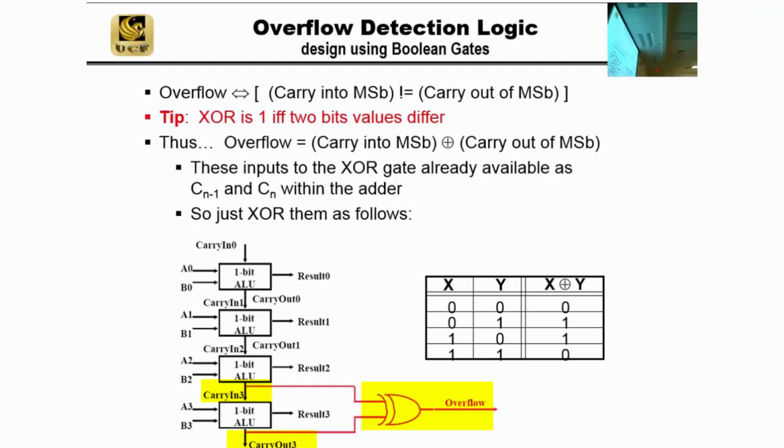If this is a 1 as a carry in and I don't get a carry out, I must have overflowed. So overflow is 1, meaning there was an overflow. Why? Because I can't represent the carry-in condition where A and B is 1 with the carry out of 1. We'll put in some numbers.